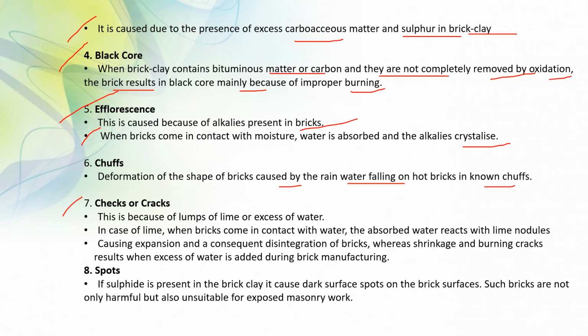Checks or cracks. This is because of lime or excess of water. Next, in case of lime, when bricks come in contact with water, the absorbed water reacts with lime nodules. There are some points given below.